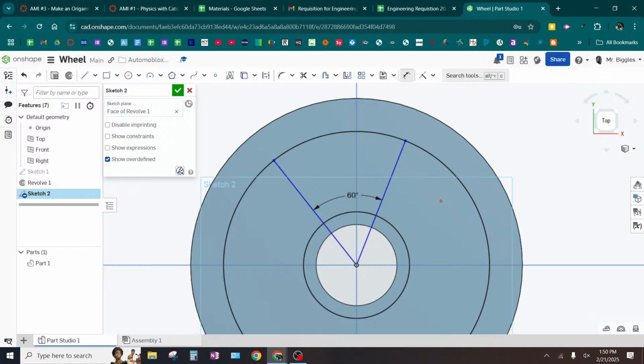I think it's good form to do something to lock this in an intelligent location. One possibility is to center it about one of the axes. Another possibility would be to take one edge and put it along this axis. I'm going to center it though. There's a really easy way to center this. One single constraint.